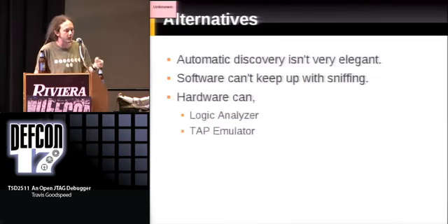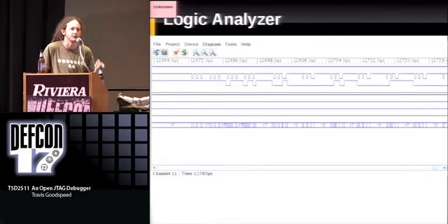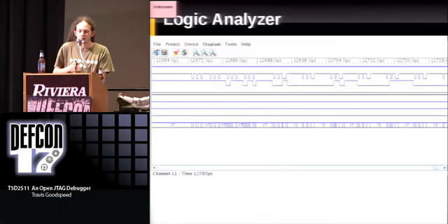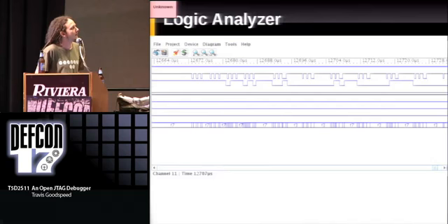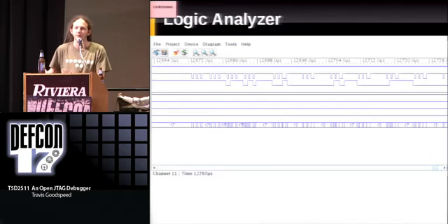This is a logic analyzer recording of an MSP430 being written by the SPI-by-wire protocol. Every one of these clumps of clock edges is actually a sequence of 4 values being written, because on each edge you choose one of the 4 lines and you write it out to the target. So if you decode this by script, and a friend of mine wrote scripts to handle it, it was quite the neighbor to do that for me, you can actually dump it out and see what's being shifted in and where.